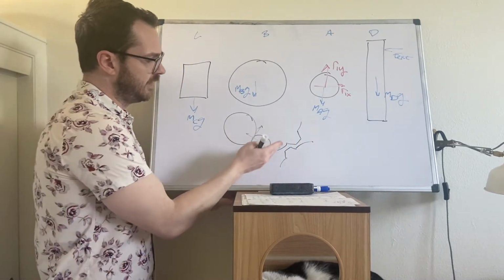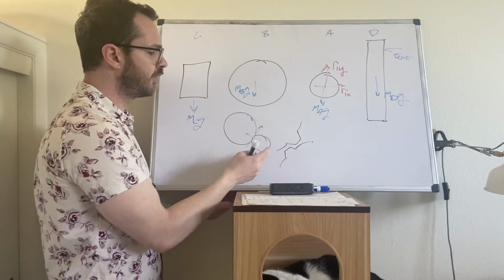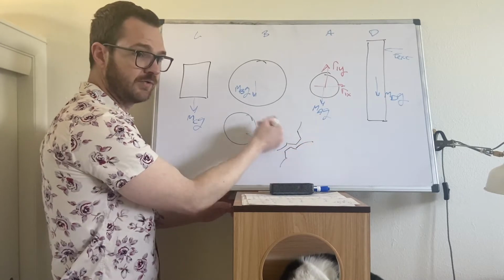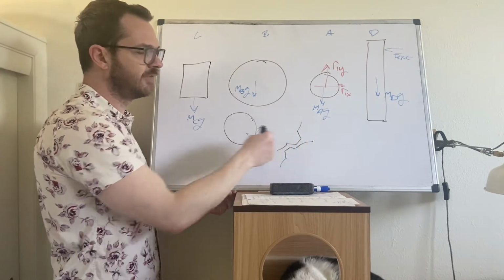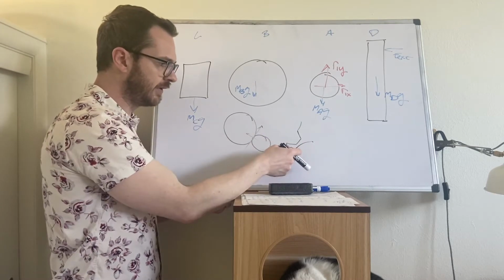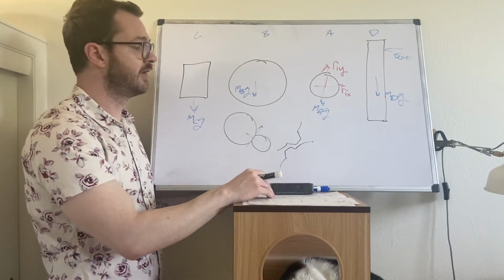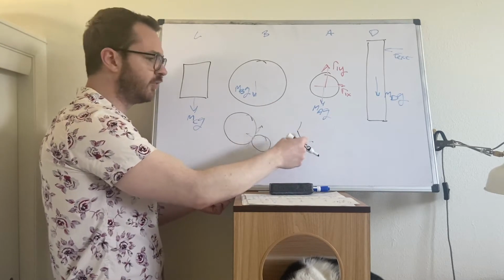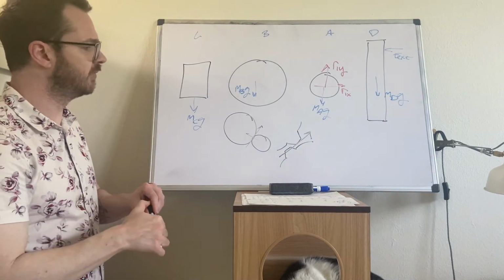Now, the force of transmission between these, right? Because one of them is going to turn, it's going to push on the other. The force between them will be tangential. There will also be a component of the force that is normal between the two. The normal component for gears is usually fairly small. You will study gears and you'll talk about the components of the force between them when you take your mechanical design classes. You'll do gear design. For now, for today, let's not worry about the normal component between them, and we're simply going to model a transmission force between the two, between the teeth.